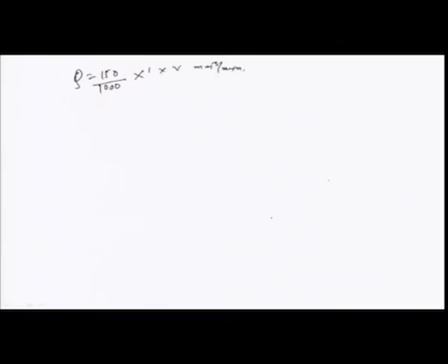You know that the slot is about 0.15 mm wide and about 1 mm thick. So this volume is coming from that cross section times the rastering speed of the beam per minute, which gives you how many mm cube per minute you want to remove.